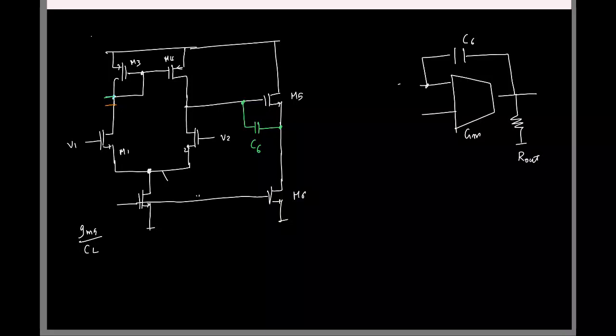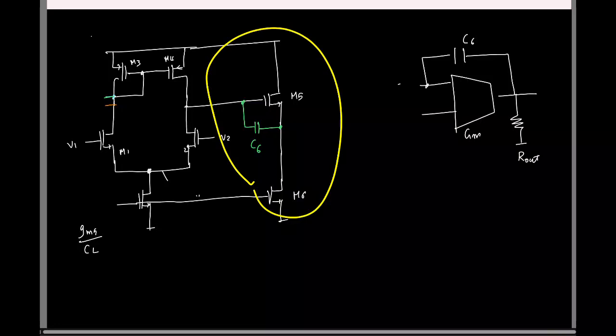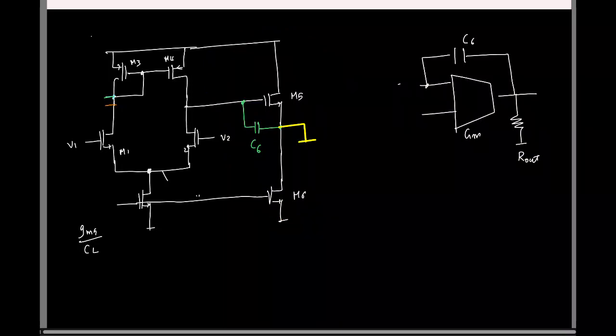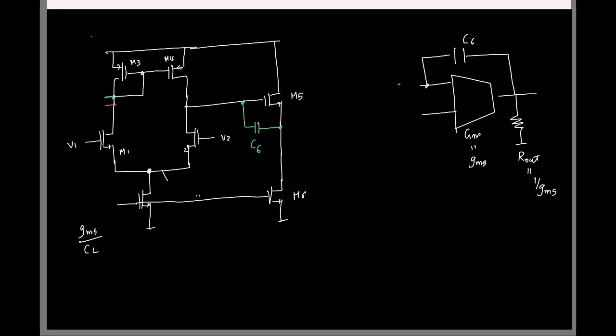Yeah, it is basically a short circuit GM for this guy. If you short circuit the output, the transconductance is still the GM of the transistor. So GM is fine. What is the R0? It's 1 by GM, that's also 1 by GM5. This is something most of you had gotten wrong. You considered this to be the output conductance R0 of the transistor, and things will go wrong.